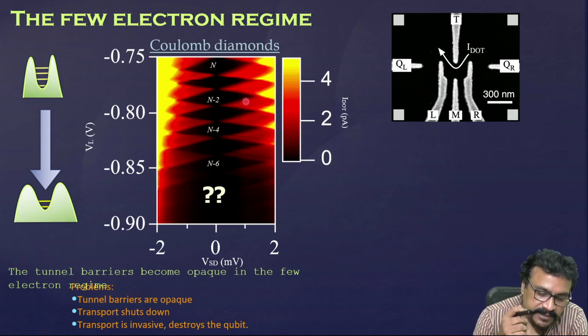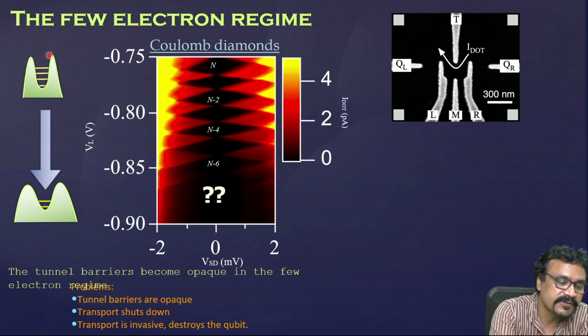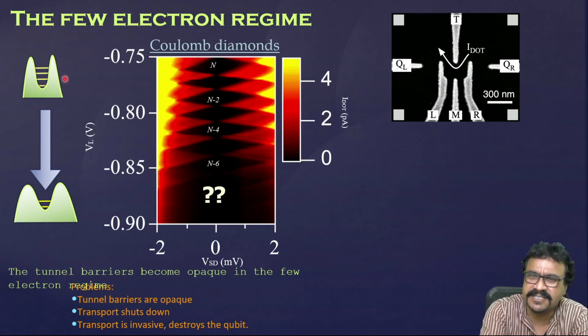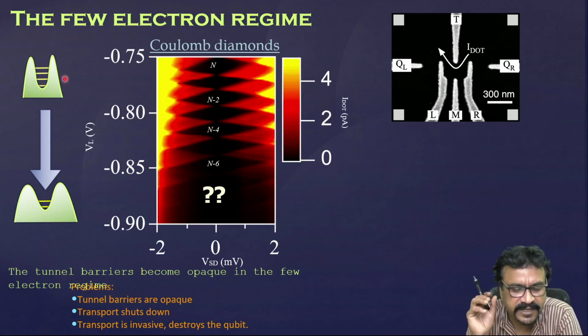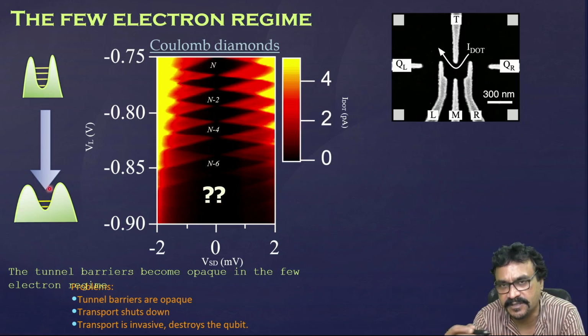And at the same time, you also make the tunnel barriers thicker. So, you start a dot with a profile with something like this. This is just a sketch, okay, just to give you a feeling of what's happening. And when you go down towards the end, you make the dot smaller, but these tunnel barriers thicker, which connects the source and drain. So, current is almost immeasurable.